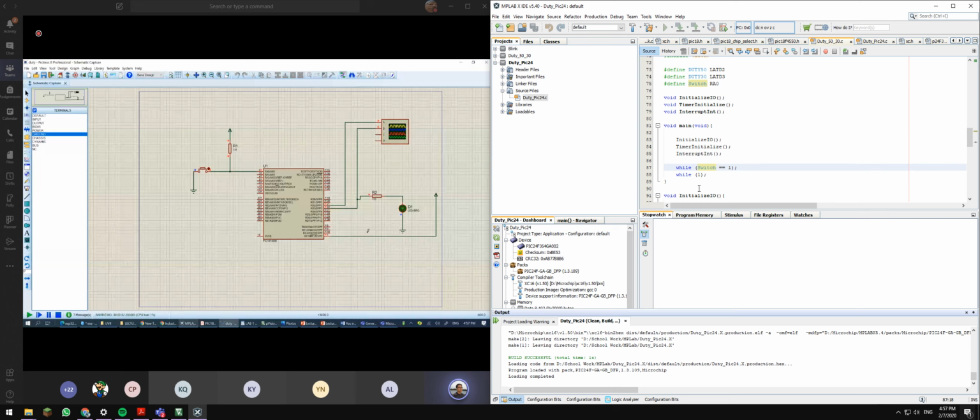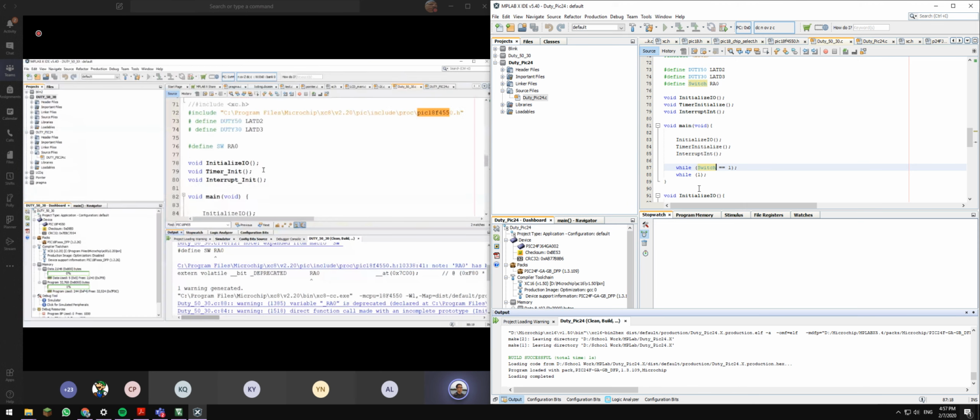It blinks, man. It blinks. How come? Is there anything I missed out in my program? Let's go and have a look. The interrupt should happen before the program runs. It's already running because my program is before the interrupt. So I should do this before anything.